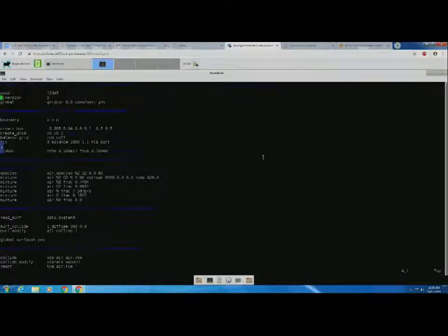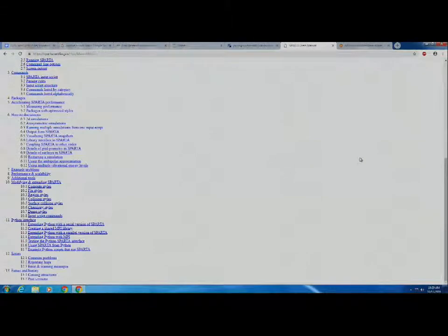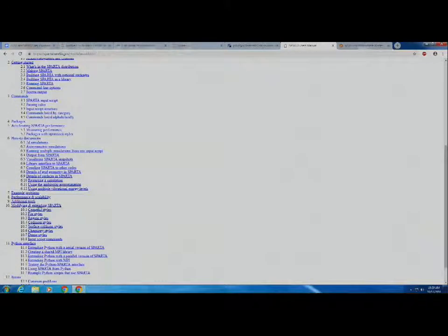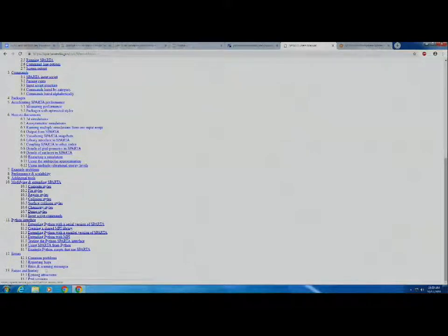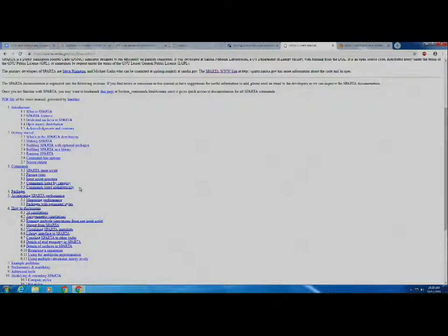So you have this dimension 2 and boundary. This is where you specify the boundary conditions. The basics are O for outflow boundary, R for reflective, S for surface, and P for periodic. And I should show, again, like I said, the manual is really good. They should all be in here. Oh, here we go. Let's just find the PDF file. There we go.